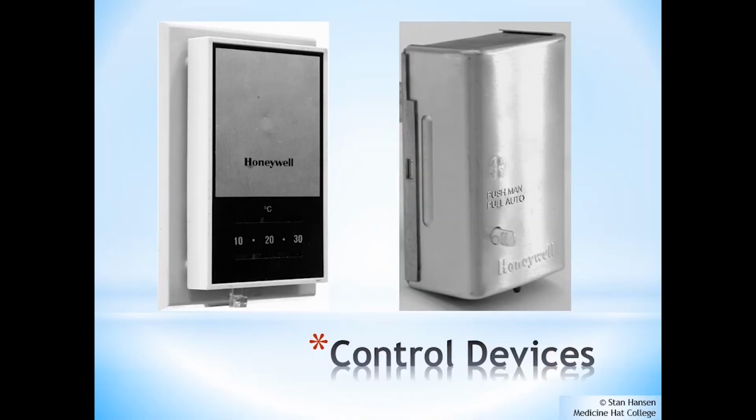In order to control the different components inside a furnace, we need to employ control devices. There are 3 primary devices that we're going to discuss. The first one is the thermostat, whose job it is to maintain the comfort level inside the rooms. It is a temperature actuated sensor based on either bimetal strips or electronic devices. The next device is called the high limit switch. It is a safety device that detects unsafe temperatures inside the furnace assembly, and it will shut down the gas valve if any unsafe conditions do occur.